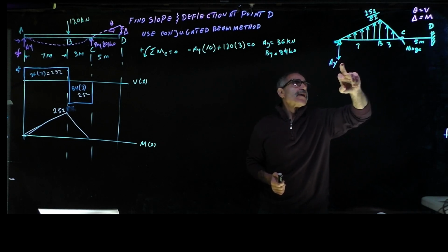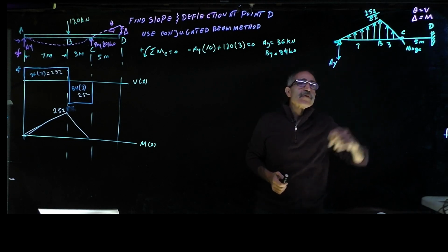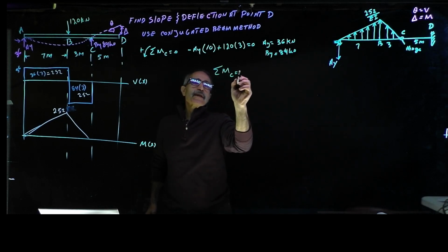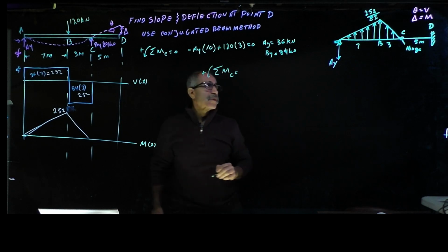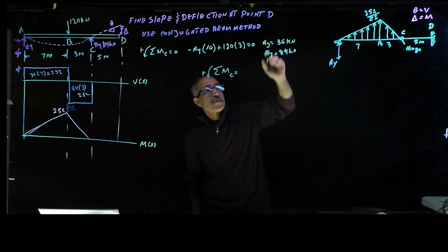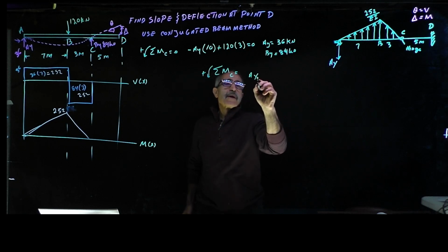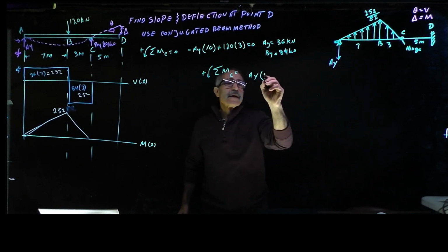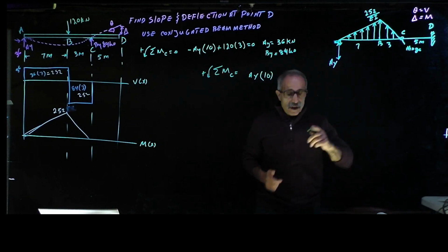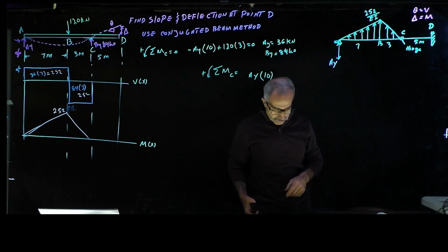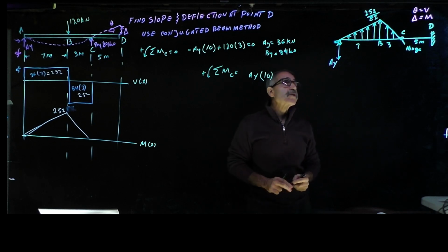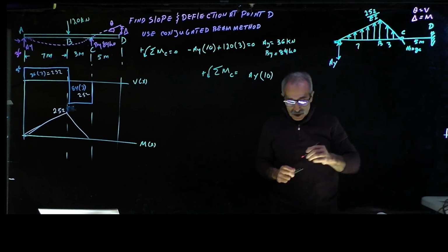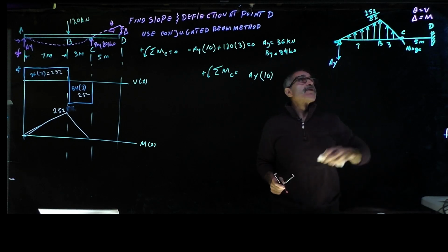Let's figure this out. Summation of moment about the hinge is 0, obviously. So we're going to take a moment: summation of moment about point C is equal to 0. Counterclockwise is positive, so that's going to go clockwise. It's going to be AY multiplied by 7 plus 3, which is 10. Now I've got to break it down here. So the concentrated force for this one is 252.